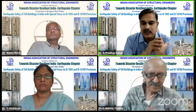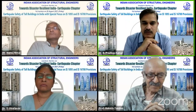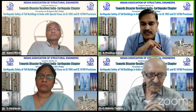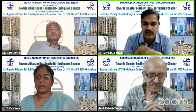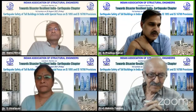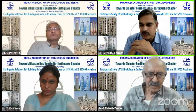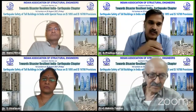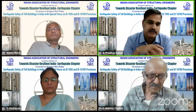Wind is a force, whereas earthquake is the displacement applied at the base. So wind force has to be calculated and applied on the structure. Wind design is elastic design, and earthquake design is nonlinear, that is inelastic. So earthquake drift is allowed up to 0.4%, and wind restricts lateral drift to 0.2%, and 0.24% for a single floor.